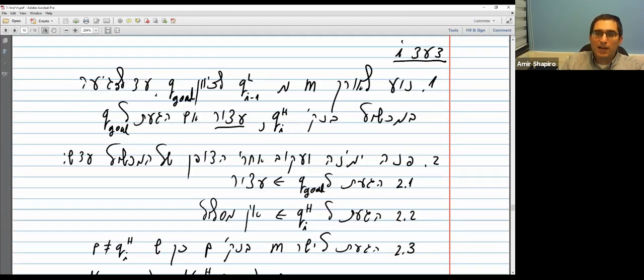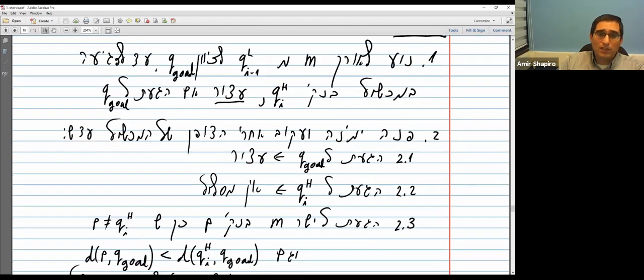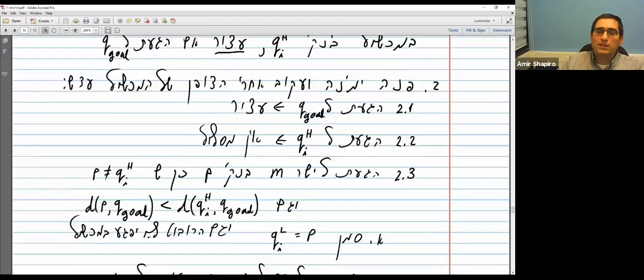Then in the ith step of the algorithm, we move along M, from the previous leave point towards the goal until we hit an obstacle at Q hit. If Q hit is the goal, we stop, we reached the goal. If not, we turn, in this case right, but it can be either left, but be consistent with only one direction.